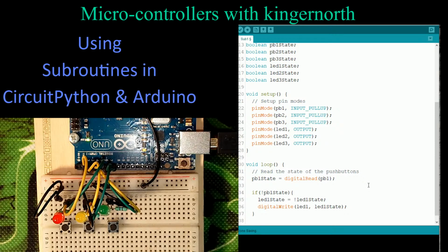And the last thing I want to add in here, something we're going to need somewhere when we press the push buttons, is a slight delay. This thing is working so fast, cycling through and scanning through the program so fast, that if I don't put a delay in here, when I press the push button, it'll go on and off hundreds of times a second, if not more.